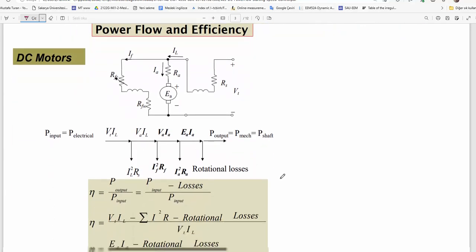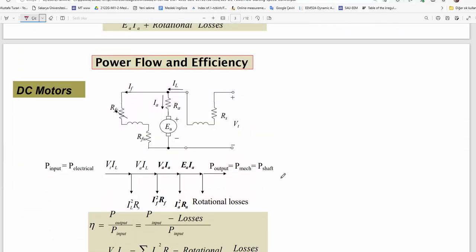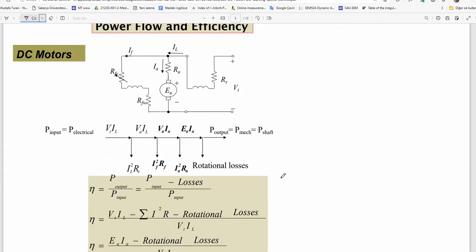Let's discuss motor operation. In motor operation, similarly, here's a loss, here's another loss, here is another loss in the compound machine. As you see, that's a compound machine in the general case, having shunt field and serial field coils. Here's an extra loss in the field controller.